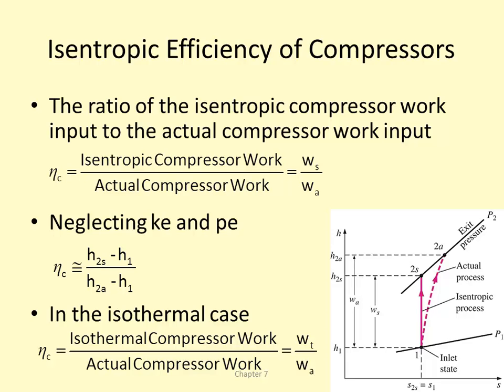And although the isentropic case is the best case scenario when we don't apply any cooling methods to a compressor, we can actually improve the performance further by applying cooling, which serves to reduce the entropy.